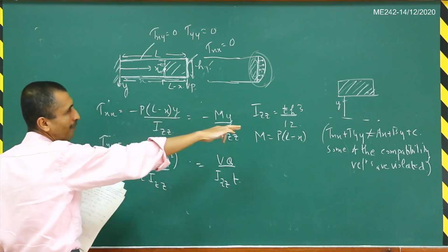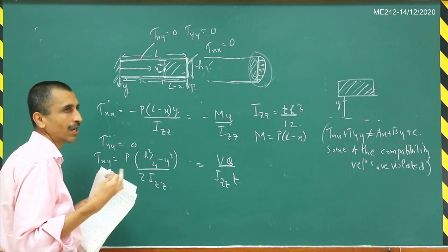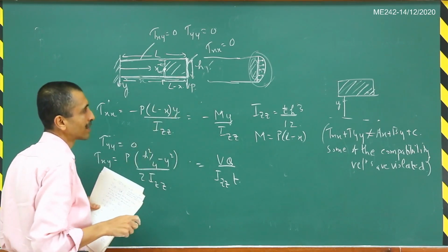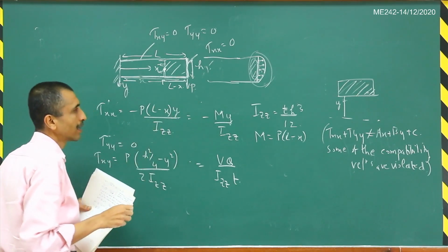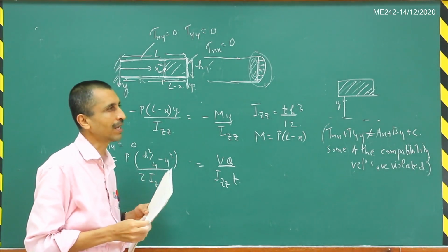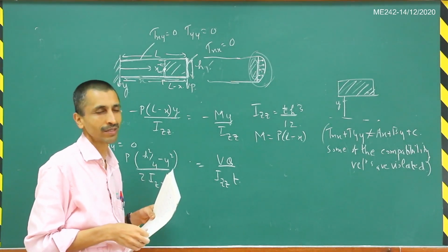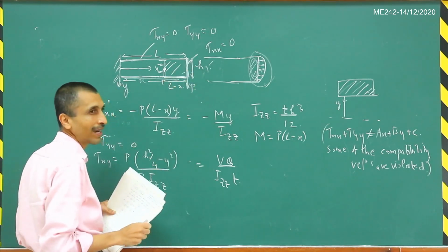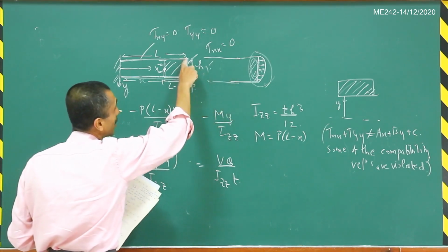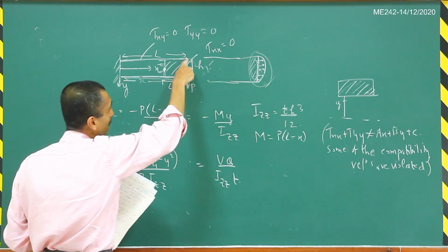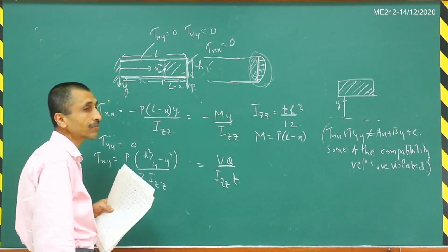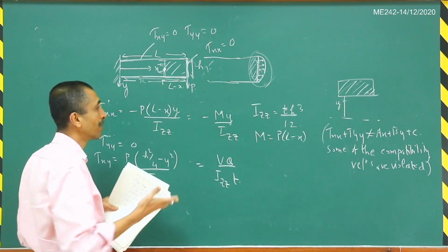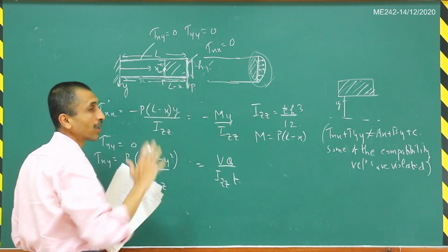That is one thing I wanted to mention, because many of you may be confused about what the use of the Saint-Venant principle is. This is the place where it is used. Basically we are saying that the exact solution is not completely useless. Obviously, if I hang a load by a thread, or apply it by a parabolic distribution, and the stress distributions are completely different, then this exact solution is of no use to me, because I am applying the load in a different way.